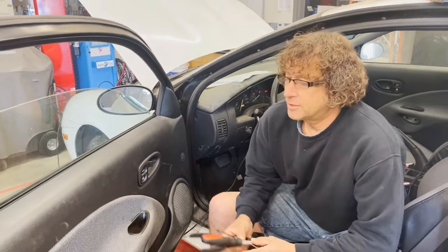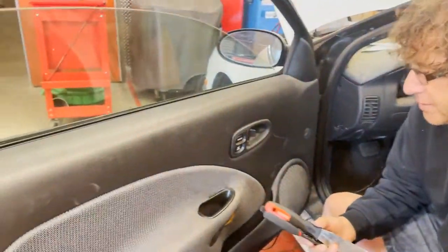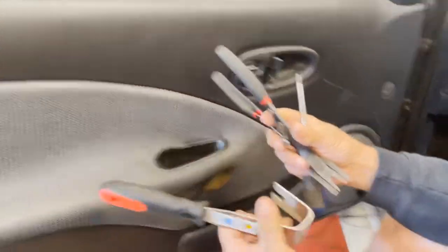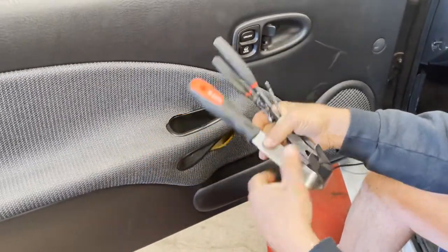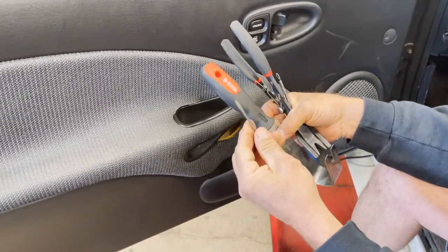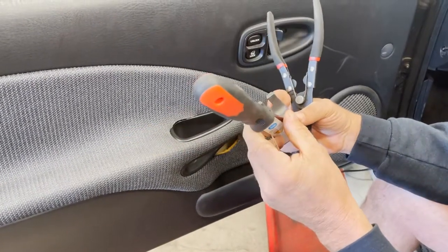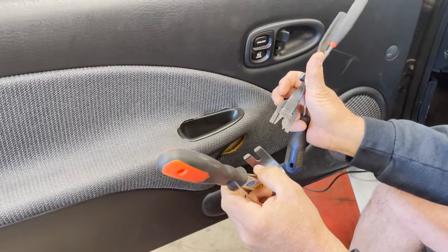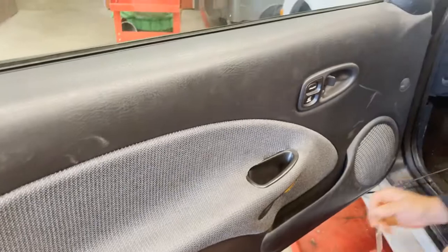Okay, we're going to go ahead and take this door panel off so we can access the window motor and test it directly at its connector. There's a lot of different tools that you might use to take door panels off. Sometimes it's just a Phillips head. I like to have a little pocket screwdriver if I have to pop off any little tabs, and then to get the major clips off that hold the panel to the door, I usually use one of these 2 tools. So let me get started taking out all the screws.